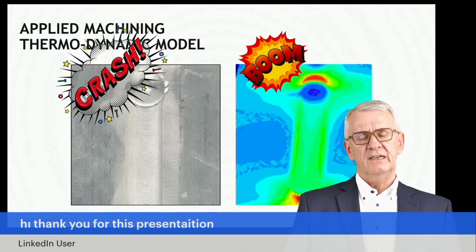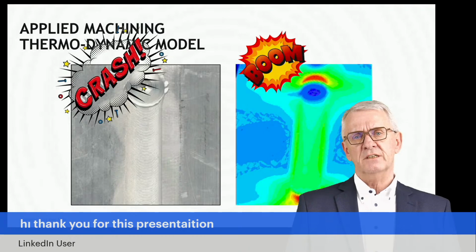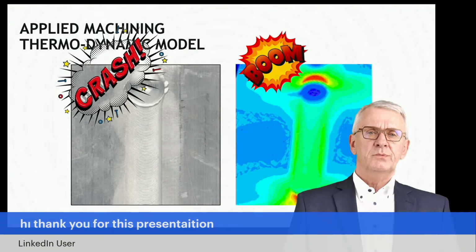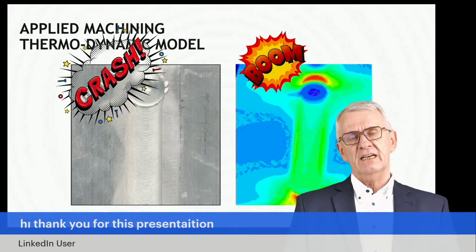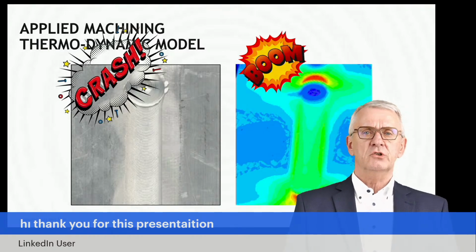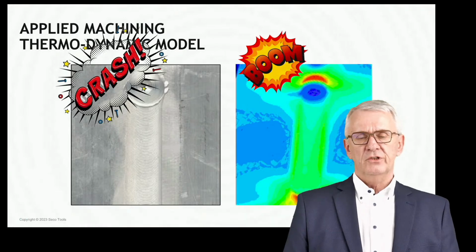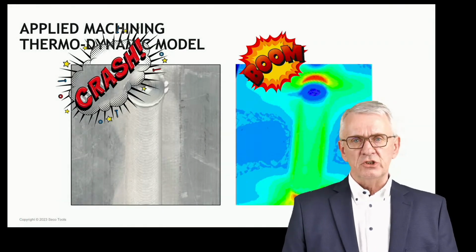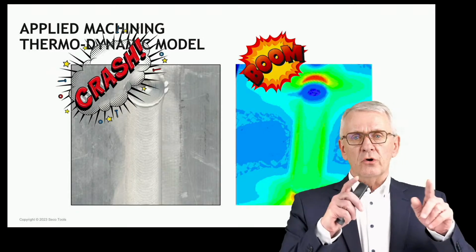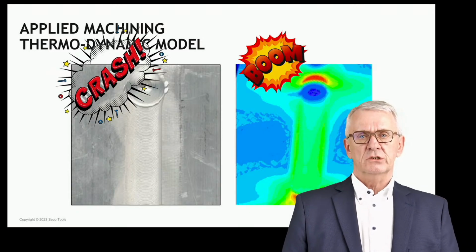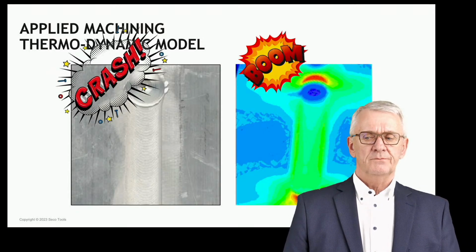So especially in titanium type materials, superalloy type materials, after a crash, it's perhaps needed to check the workpiece not only from a mechanical perspective, but also from a thermal perspective, in case you made by any chance some thermal treatment which is unwanted.